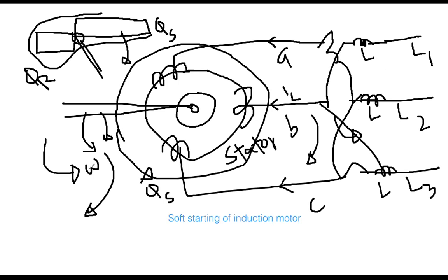Then next time you will see that my direction of rotor is as expected, as prescribed on the manual or on the system. So while you are doing lab experiment number 3 and 4, you might face this issue. Typically no, but sometimes it happens. It depends on which machine you are using. If you notice that your motor is rotating in the opposite direction as prescribed, then immediately you stop and then you just interchange.